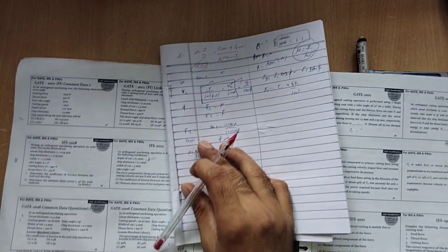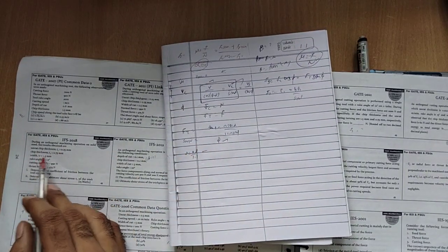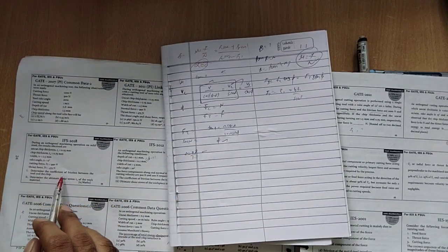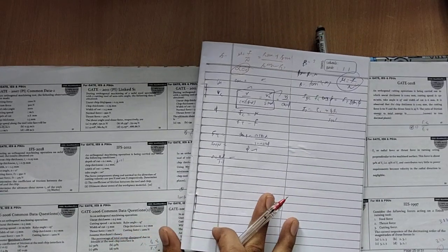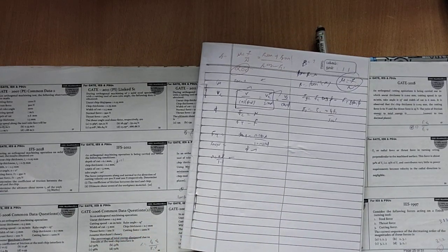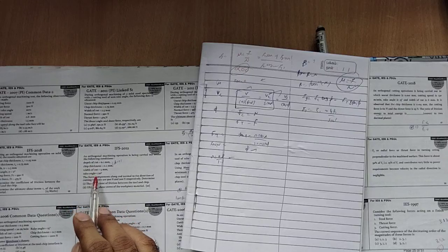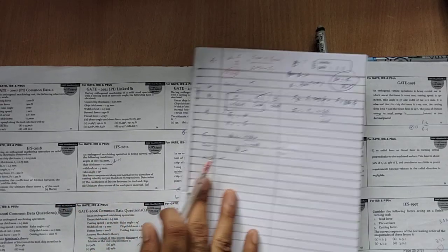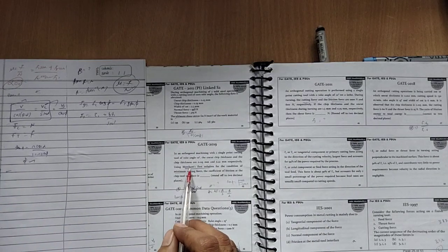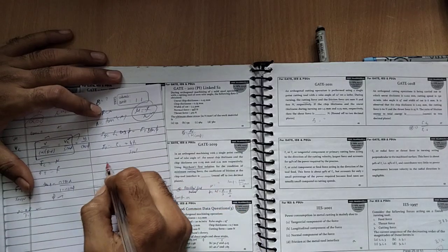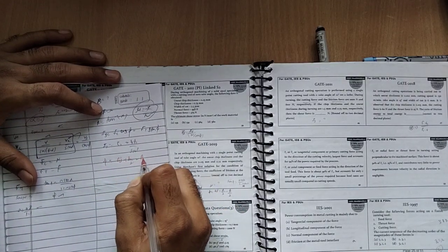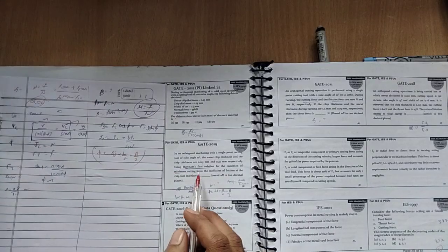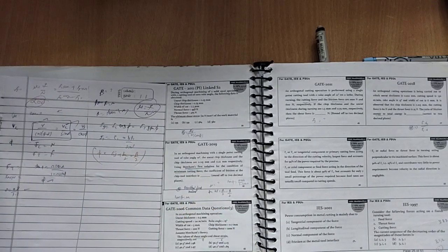So next one you can see, during orthogonal measuring, T1 chip thickness. Okay, with the cutting force, determine the coefficient. This one I think I can easily do it. So depth of cut, chip thickness and width, this also you can do. So you can see merchant first solution. Merchant first solution means 45 plus alpha divided by 2 minus beta divided by 2. Put here and calculate 10 degree, and so the coefficient of friction at the chip.